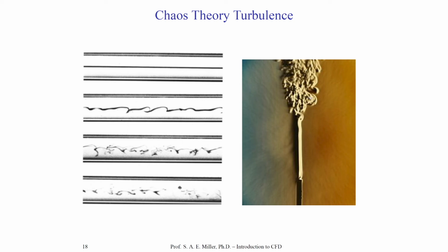It's very likely at any time for this flow that we'll always have a unique vector field of the turbulence. That means any small perturbation around this little incense stick would produce completely different solutions at a later time. This is very troubling for the prediction of turbulent flow, and is helpful for the explanation of why we're using turbulence statistics for prediction of turbulent flows later in the class.